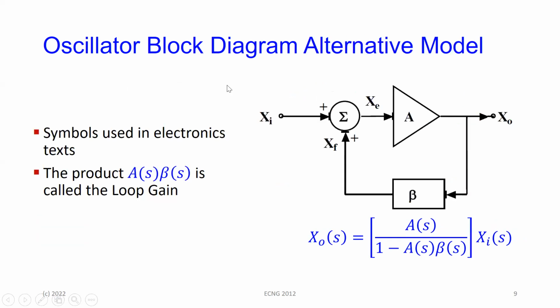Right. So the part A beta is what the textbooks call the loop gain. So anytime you're reading something or some of the handouts that I have, I'll put up another handout for this, anytime you get a handout and you see something where the loop gain is so and so, they're referring to A beta. Notice I've changed it again to the amplifier symbol. So A, the forward block, beta, the feedback. A multiplied by beta is the loop gain.